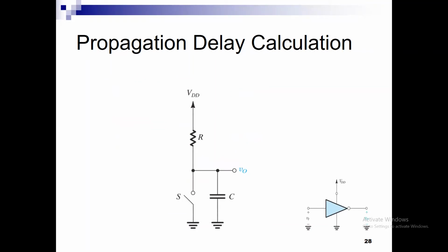Great. For the propagation delay, I know my C. I have to know my effective resistance. For the resistor-based inverter, one type of the delay, particularly the TP low to high, is simple for me because when the output is rising, this corresponds to the input dropping to 0.